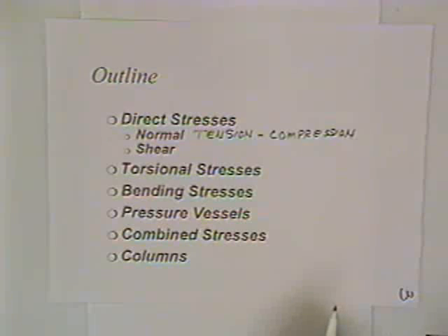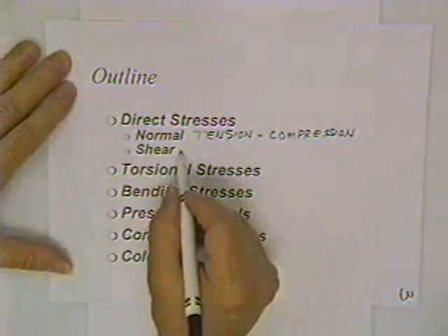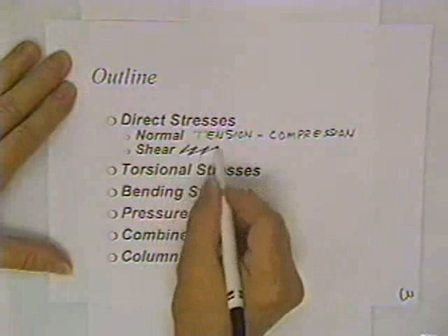Compressive stresses would be the type of stresses that would be in something when you press on it. And shear stresses are slightly different. Shear stresses are wiping stresses. Those are shear stresses right there, when you rub your pencil across a page and little pieces of it come off on the page.